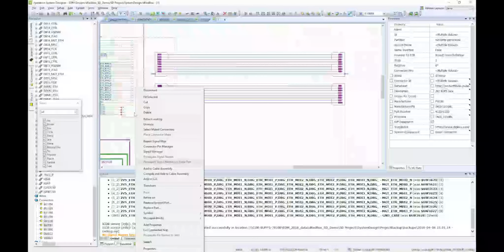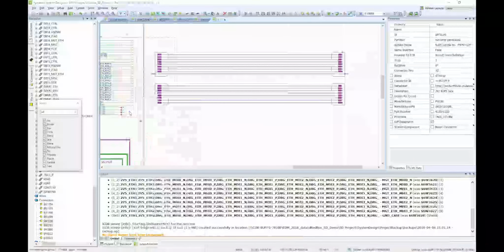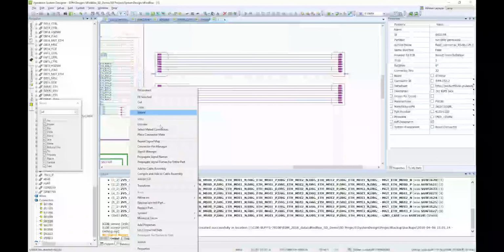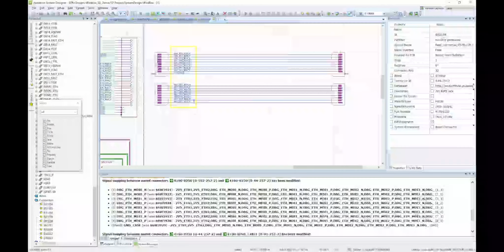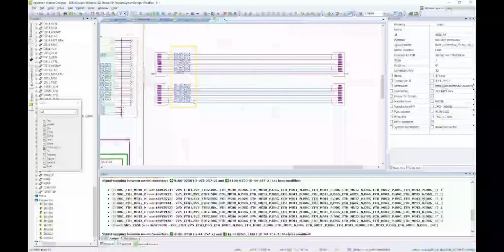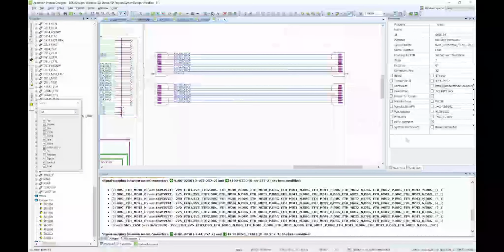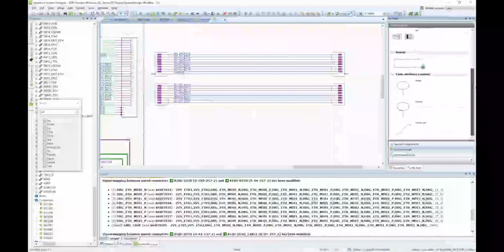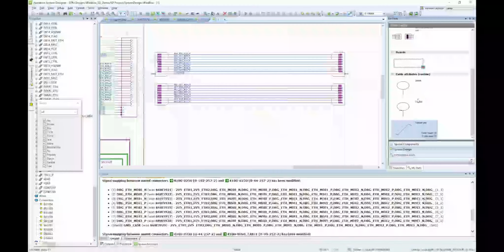After mating occurs, you can see the mate indications traversing from male pin to the female pin. When mating the next pair of symbols, the remaining slot is automatically selected. After the connectors are mated, the wires can be named with a simple command, propagate signal names.